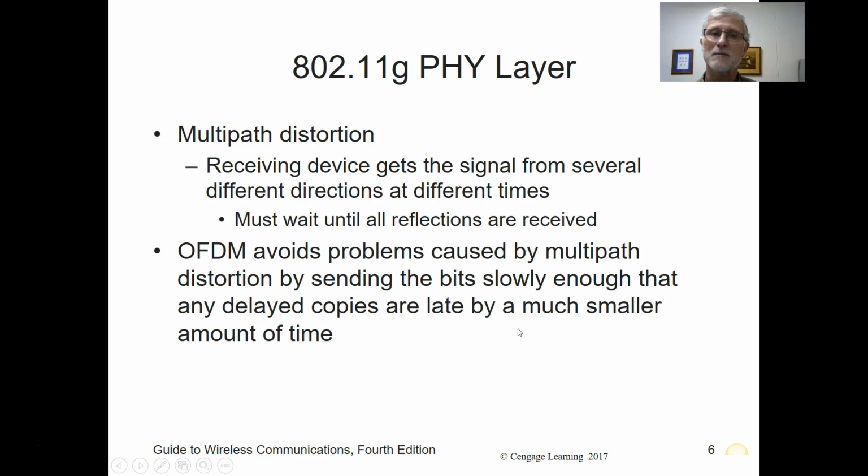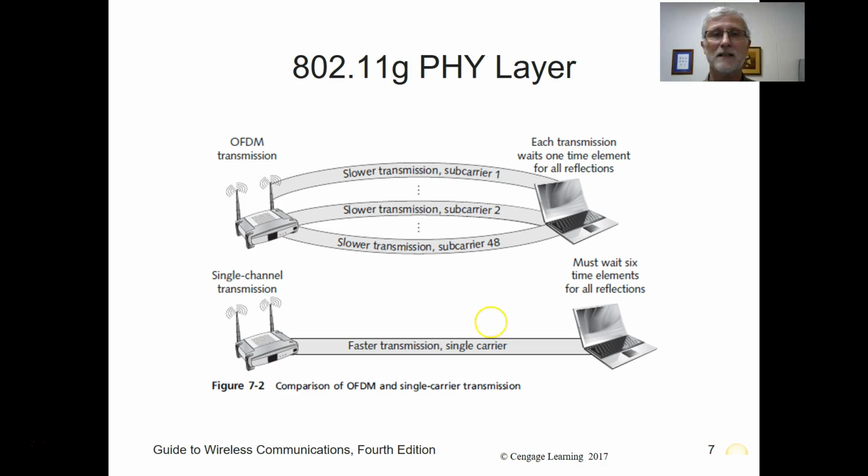Now, the reason they did this because they says, hey, especially in a wireless environment, the signal gets bounced around a lot and it gets distorted. And if I can get the antennas to receive from different signals, different places, different times, I can kind of allow that multi-path distortion to kind of help me understand and create a better signal, or at least reception.